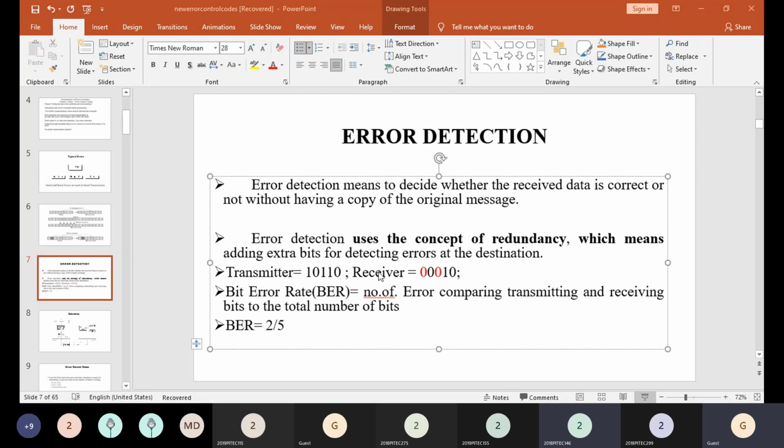Then you need to calculate the syndrome. Syndrome, as you know, is nothing but the received code word with the error, multiplied by H transpose, the transpose of the parity check matrix. Syndrome is nothing but R into H transpose, or the error pattern E into H transpose. So you'll be having the error pattern generation. Depending upon the length, the error pattern will change, whether it is going to be a linear block code or a Hamming code.